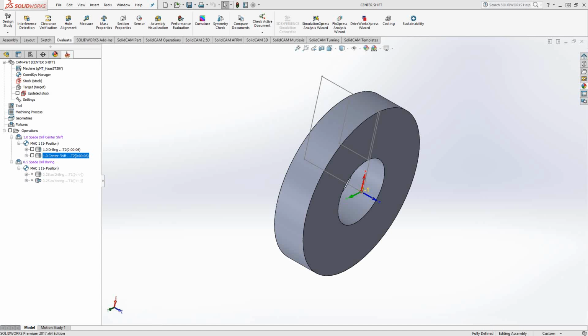A lot of people have different names for these things. I usually think of it as an insert drill. It's basically a shank that has a drill kind of quality to it, a drill flute, and then at the tips they have inserts that allow you to do either just drilling or drilling and boring. So in this video, I'll show you how to use that type of tool that can exist as both types.